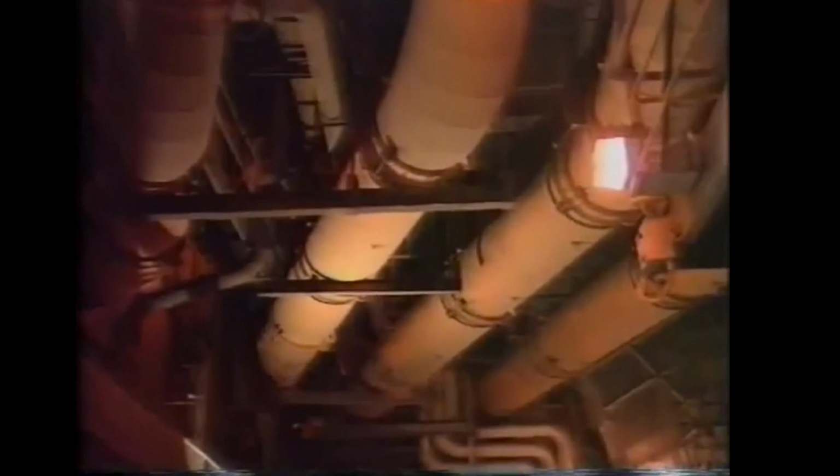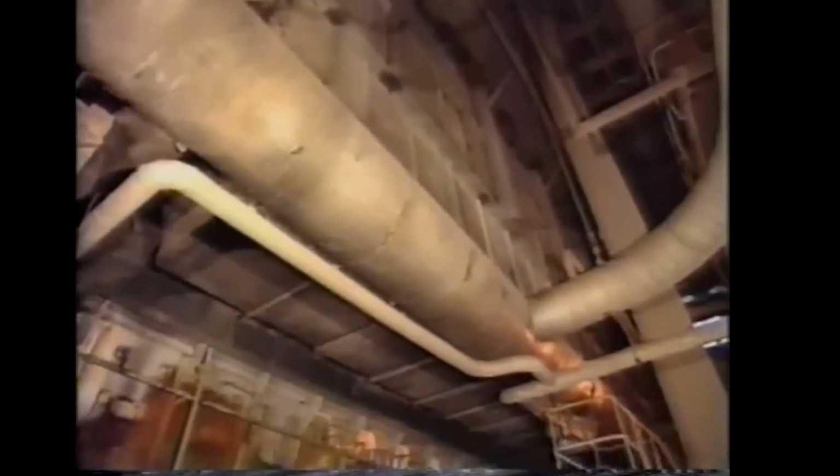The coal is crushed into very fine powder in these pulverizing units. That's done for two reasons. The smaller the pieces, the greater the surface area available for reaction during combustion. It also makes the fuel easier to handle. It can be blown with hot air as a fine powder through pipes and into the boiler furnace. In the furnace, the fine coal burns like a gas.